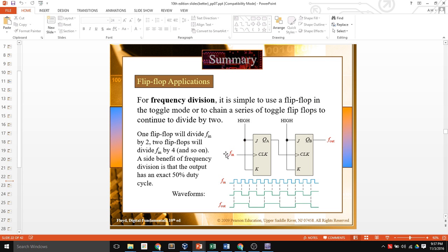So here is an example of how to build a counter with a flip-flop. So if I have 1, 1 on my flip-flop, it just toggles whatever Q was, it becomes Q naught. Every clock cycle, it'll change over and over again. So if I start with a 1 in here, then the next clock cycle, the rising edge will make that a 0. The next clock cycle will make that a 1. Next clock cycle goes back to 0.